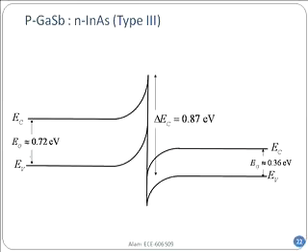You can do that, and when you do, you see that this again is, let's say, p-type on the emitter side and n-type on the base side. Do you see now the band gaps on the two sides? The band gaps are not inside each other at all. It has been completely shifted out.